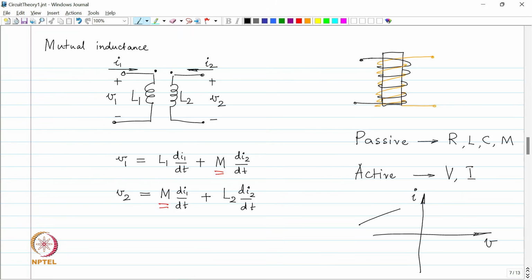And what about this device? It produces power, right. So, any device which is operating in the second quadrant will be active. And what about the third quadrant? If it is over here, passive. And what about here? Active. Fine, are we clear? So, the passive device operates in first and third quadrants only, active device operates in second and fourth also.